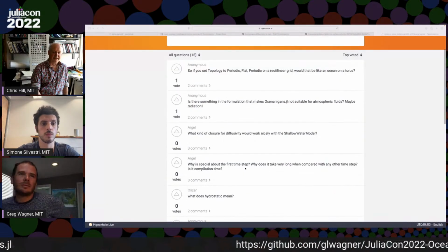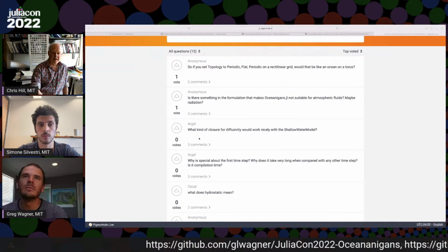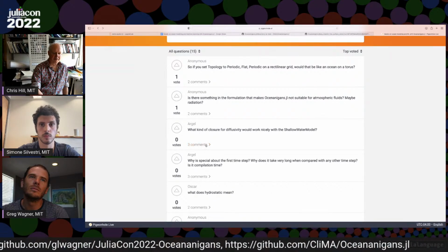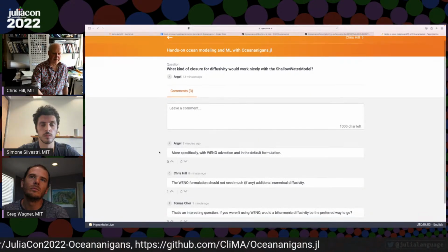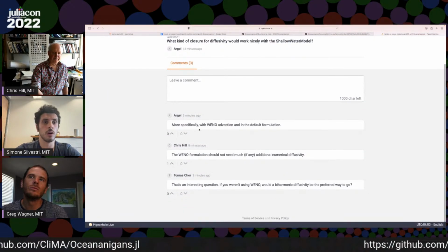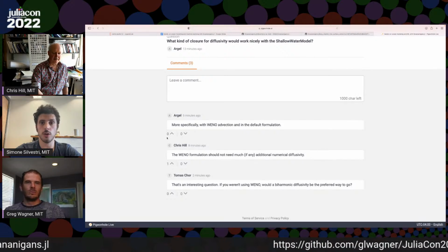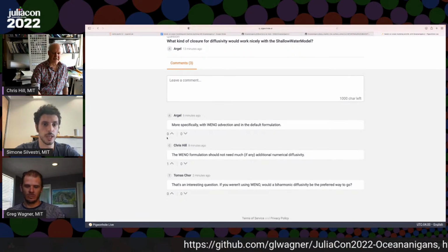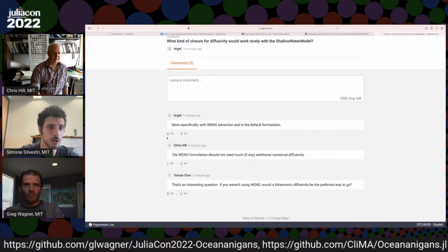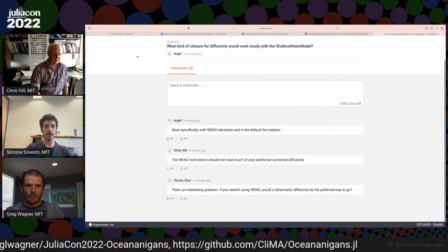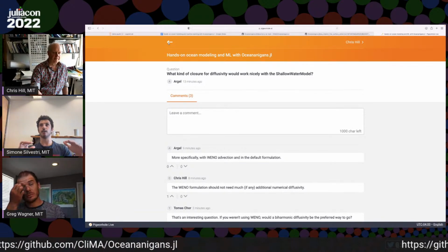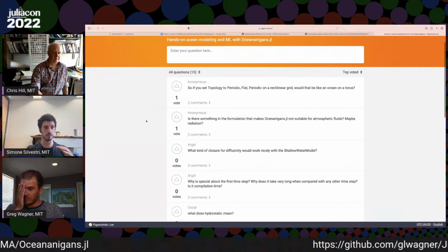And then I think Argel, this question in particular was asking about WENO. Simone, do you want to say a tiny bit about WENO and diffusion? Because Greg was looking at centered second order. Yeah. So with our WENO scheme, we actually have inbuilt diffusion. So we don't need to add some explicit diffusivity, because WENO should actually take care. It calculates the reconstruction dynamically based on the field.